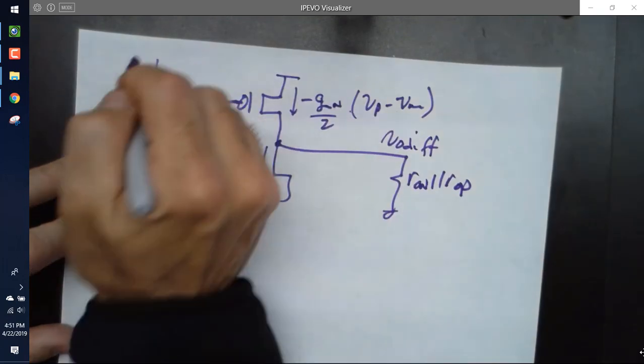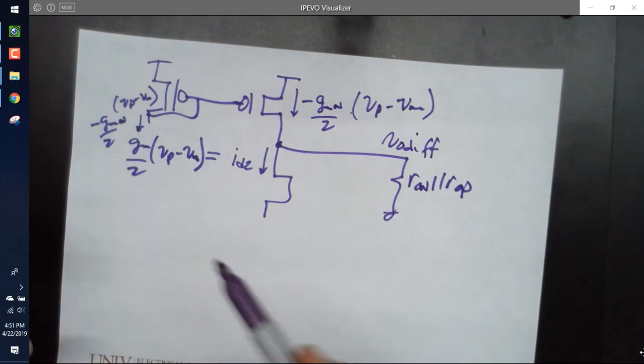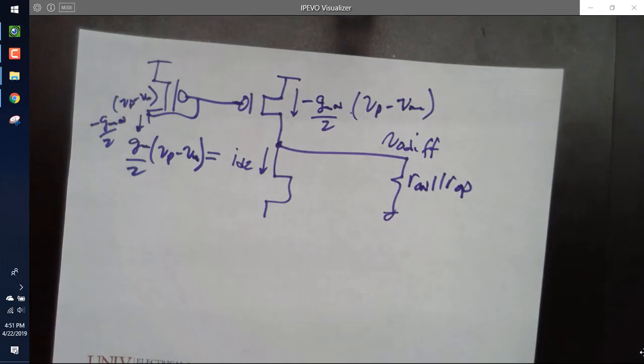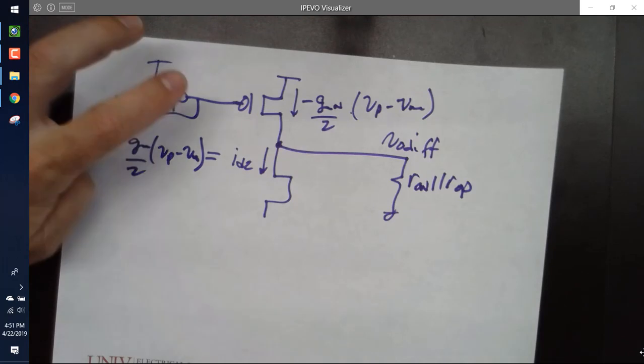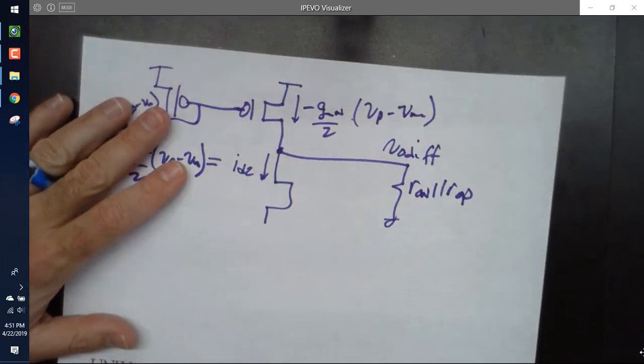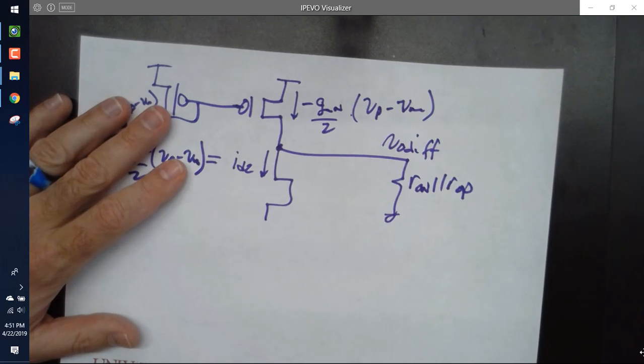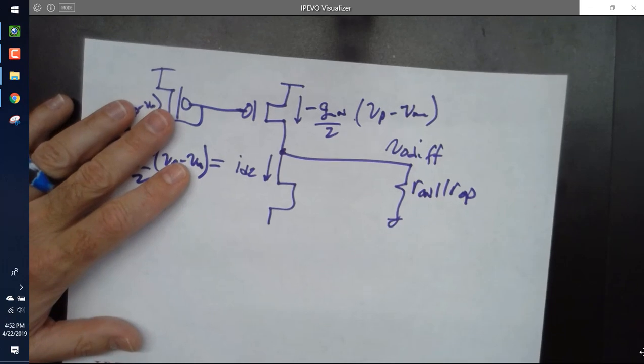Why is it gmN and gmN here through the PMOS? Because the current's coming from the diff pair, and then it's going through the PMOS current mirror. I almost asked today in the quiz, I had the reference, and I'm going to ask them why, at the top of the reference, the VGSs don't come into play in the temperature behavior and the calculation of the current or reference voltage.